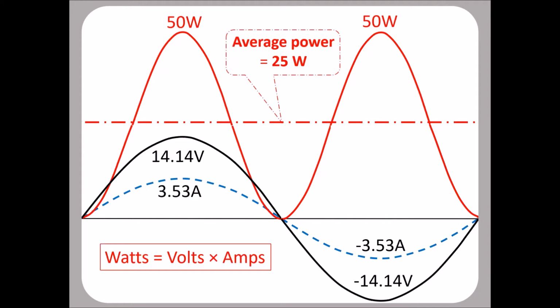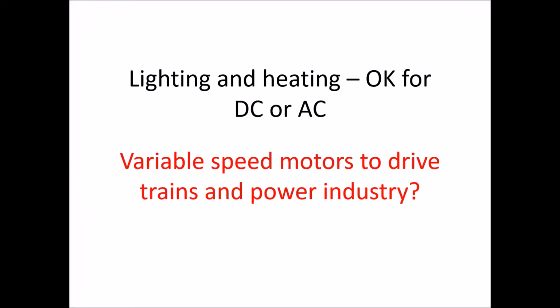Well, one of the reasons that settled the frequency originally when the business started up was that with the incandescent lamps at the time, if you had a frequency below about 30 hertz, the pulsations were perceptible. And it was very irritating. So the decision was inevitable. We're going to have to drive the generators around faster to stop people getting a flickery view.